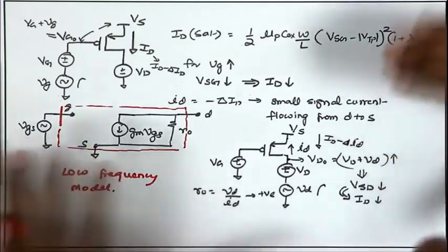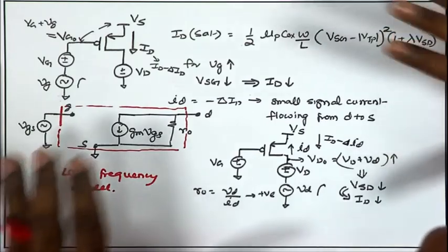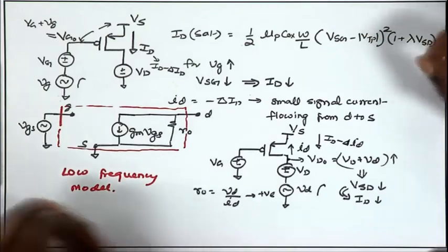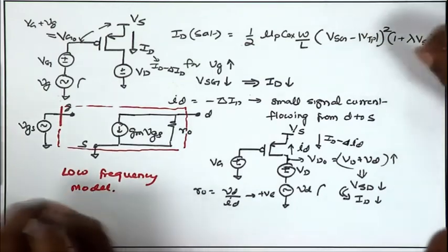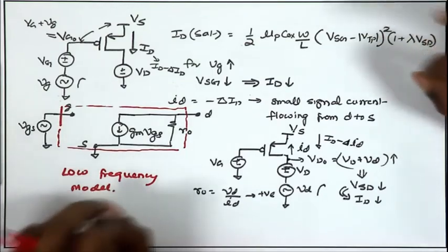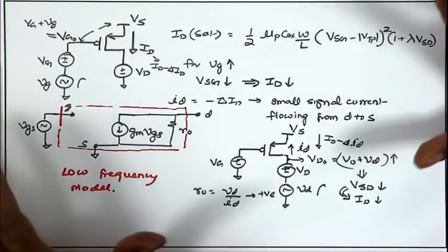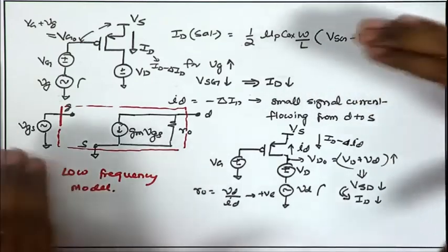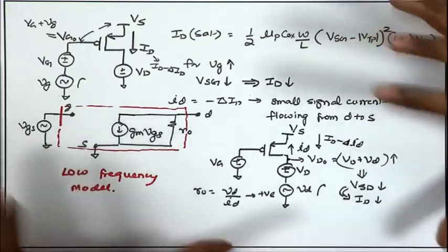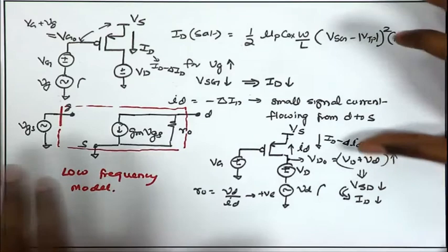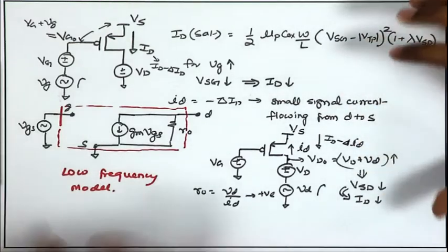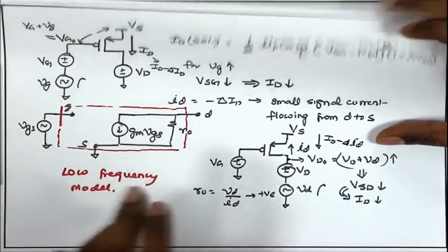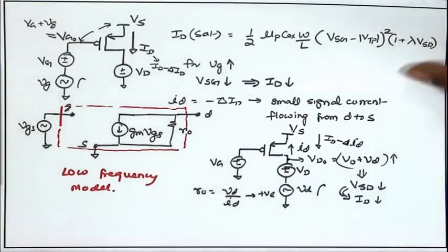Likewise, when you are talking about parasitic capacitances, they are ideally not supposed to be there. We do not want them, because they are going to limit the performance of the MOSFET and the circuit that we build with those MOSFETs. They are undesirable effects that come inherently from the device physics and the device operation of the MOSFET. So, let us first understand the basic mechanism of those parasitic capacitances, and how we define and quantify them and include them in the small signal model.